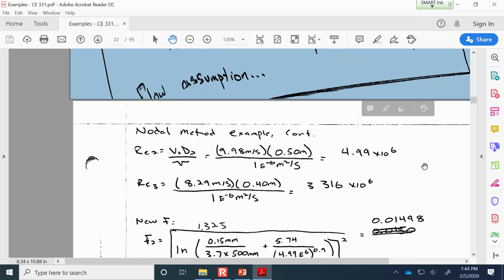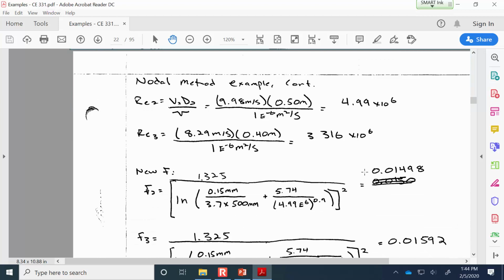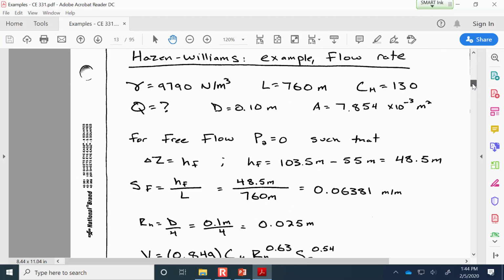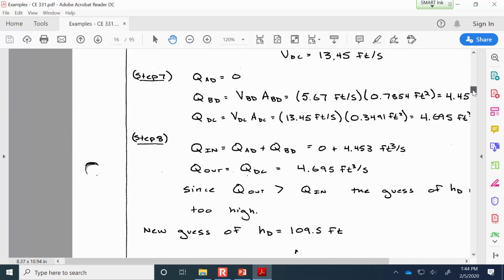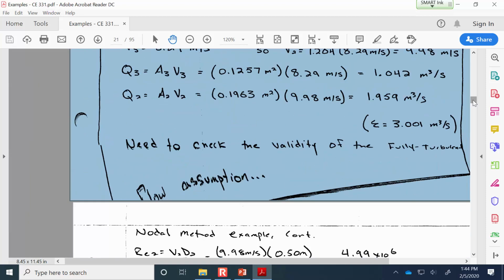That's all right. Check by calculating the Reynolds number through each pipe and calculating a new F value. So now this is the full Jain equation instead of just the fully turbulent flow. For pipe 2, when we used fully turbulent flow, the F value really went too high.